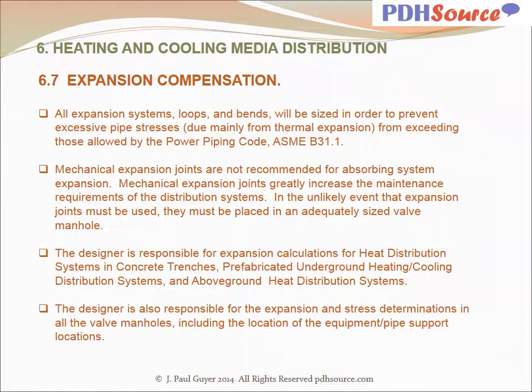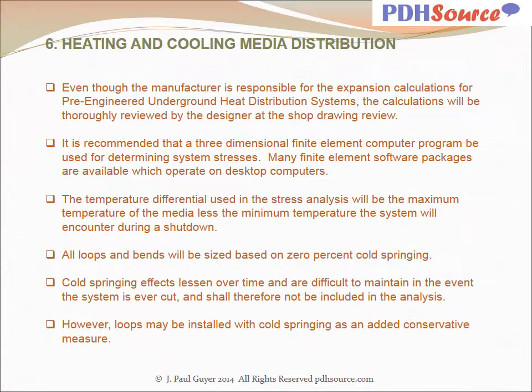The designer is responsible for expansion calculations for heat distribution systems in concrete trenches, prefabricated underground heating cooling distribution systems, and above ground heat distribution systems. The designer is also responsible for the expansion and stress determinations in all the valve manholes, including the location of the equipment pipe support locations. Even though the manufacturer is responsible for the expansion calculations for pre-engineered underground heat distribution systems, the calculations must be thoroughly reviewed by the designer at the shop drawing level.